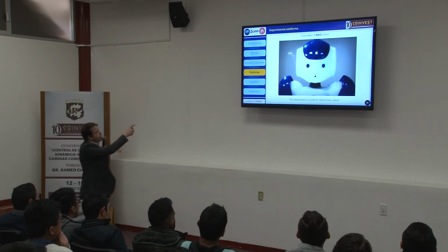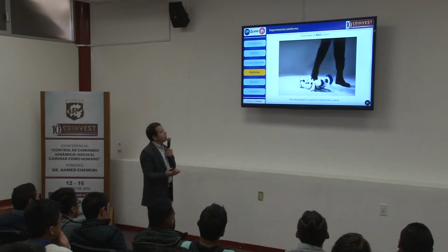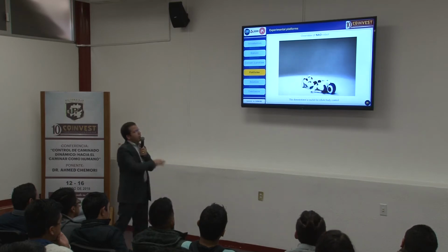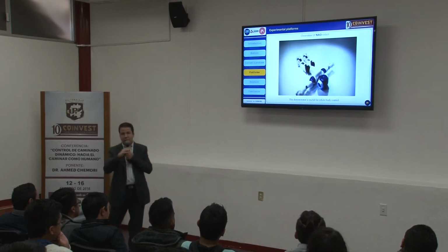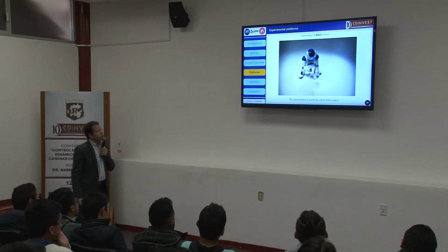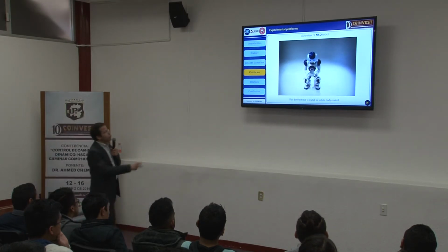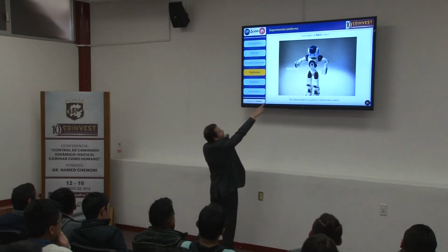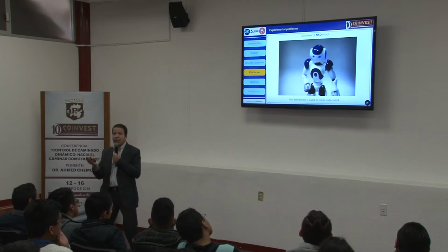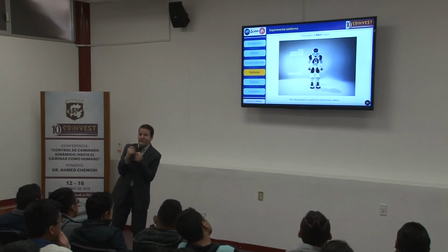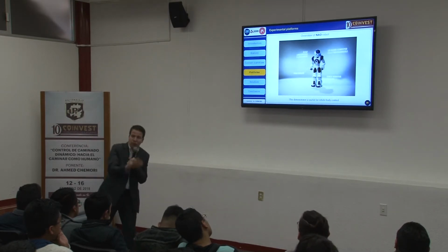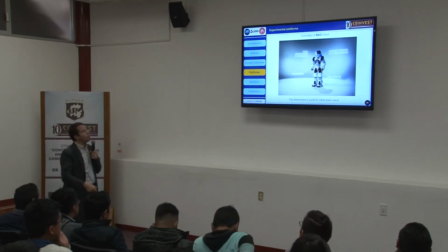He has also legs, as you can see. Oh, the same problem as previously. So if he falls down, he has the possibility to get into the upright position, as you can see. He has just to execute this motion. And as I said before, the IMU, the inertial measurement unit which is inside here, helps you to detect this falling down, such that you can prepare yourself to avoid breaking the robot. So he prepared himself to get to the good position while falling down.